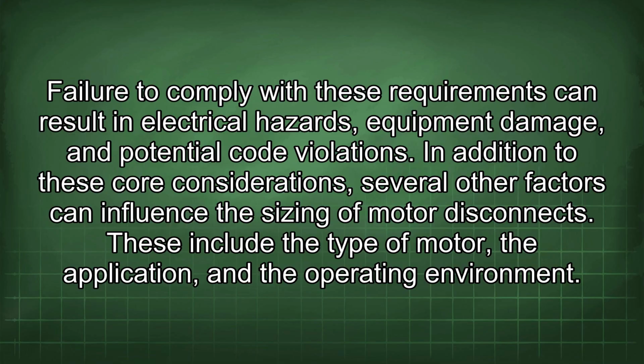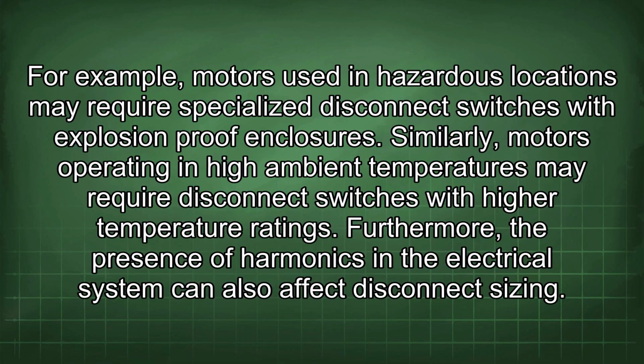In addition to these core considerations, several other factors can influence the sizing of motor disconnects. These include the type of motor, the application, and the operating environment. For example, motors used in hazardous locations may require specialized disconnect switches with explosion-proof enclosures. Similarly, motors operating in high ambient temperatures may require disconnect switches with higher temperature ratings.